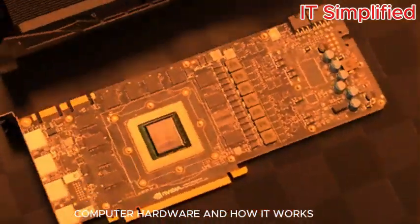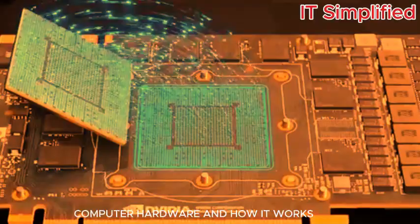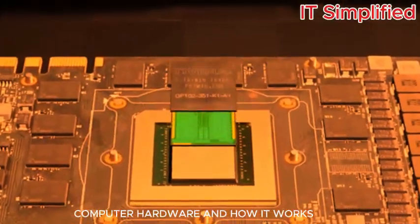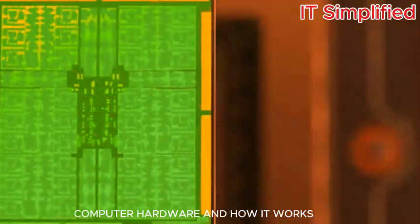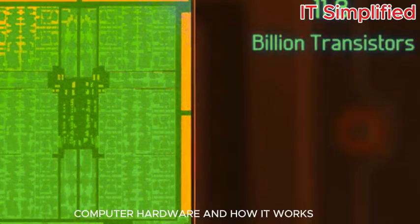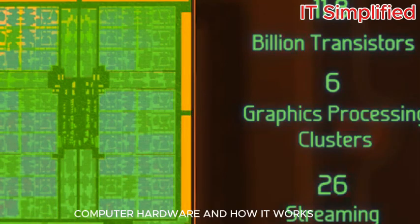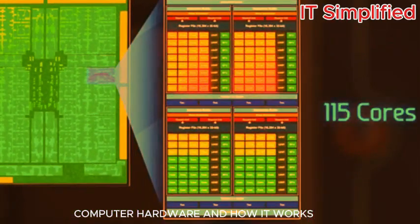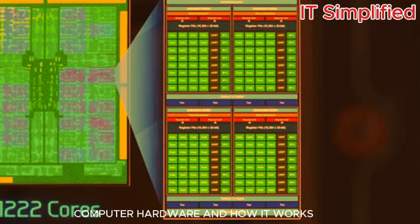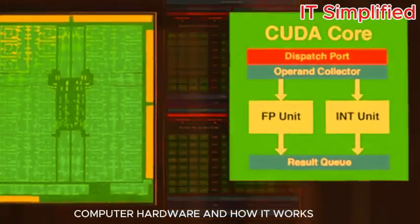Let's focus on the GPU integrated circuit, which, similar to the CPU, has more than 1,000 solder pads that connect it to the PCB. Opening the packaging, we find the GPU die, which is noticeably different from the CPU. In here are approximately 11.8 billion transistors, organized into 6 graphics processing clusters, totaling 28 streaming multiprocessors. Each streaming multiprocessor is composed of 128 cores, resulting in a total of 3,584 cores.